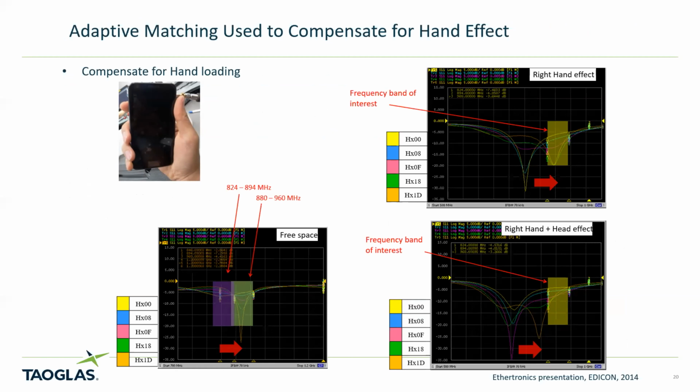And once that was done, it occurred to a design group that, hey, we're able to send frequency information and retune for a lower band frequency response, but also there are proximity sensors and a few other functions in the phone, speakers, microphones. We can actually make predictions as to the use case and retune that capacitor to compensate for hand loading or hand and head loading. So that's what was done. This is an example of an open loop active impedance matching technique that went into production in a commercial device.